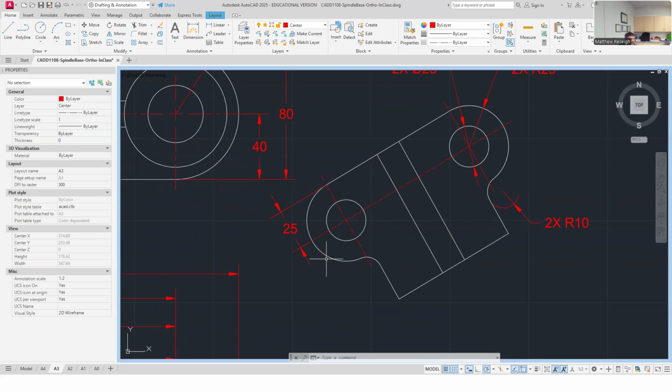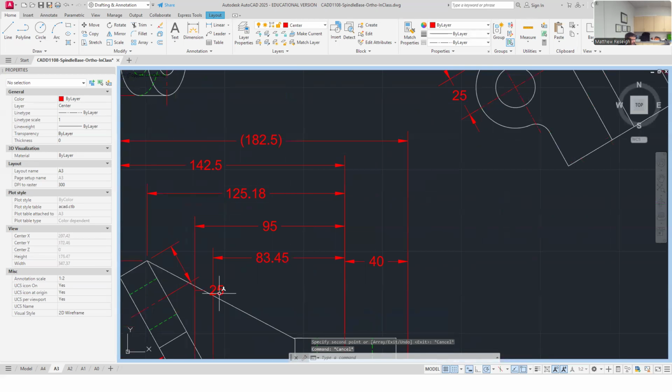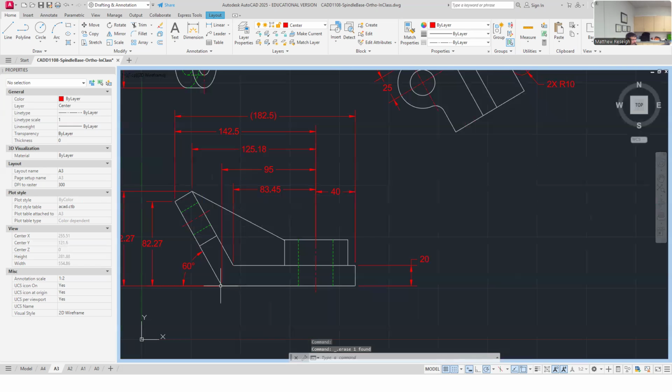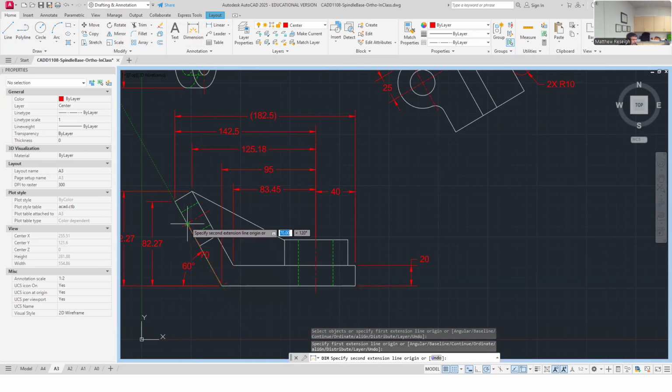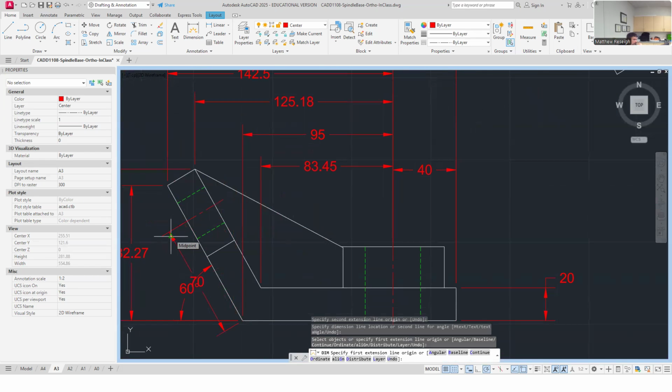Good. Sized and located in one direction with a new datum, kind of. So I might have to come back and analyze that later down the road and ask, is that the best way, or should I figure out a better way? Would it be better if I pop this one in here? Either way, it's pulling off a different datum. It would be arguable that I should pull off from here then to there. And in the event that I did work in an industry where they like these aligned dimensions, this one might be a better controlled location for that, from that corner datum that's based off the base. It's argued this may be better.